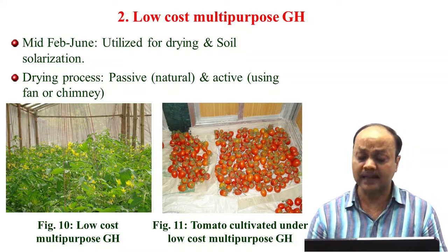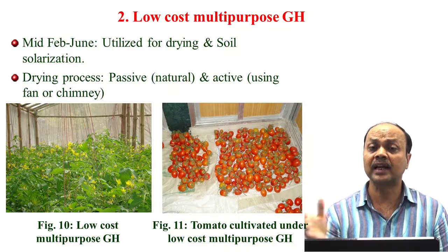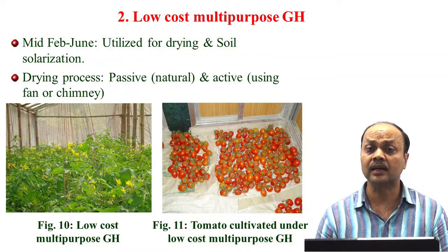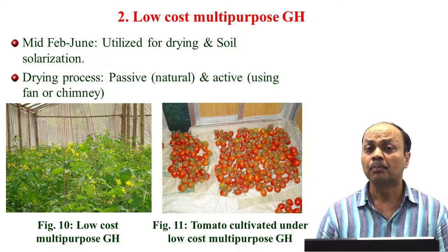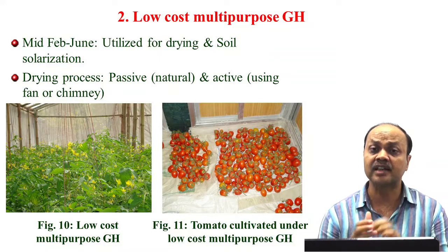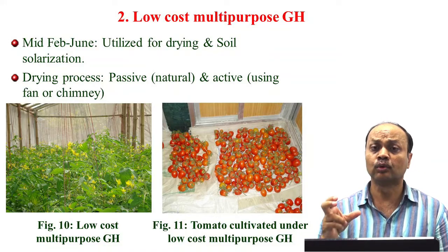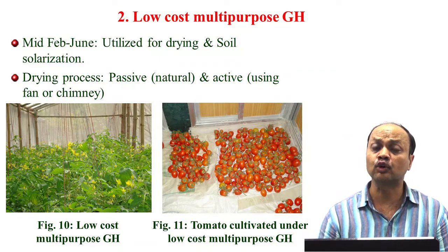So what I am saying, as I told you, is that due to high temperature we can harness it, but there are various factors that affect the drying. In this course, the other teacher will discuss them with you later on, but briefly I can say: temperature, relative humidity, air velocity inside the structure, and, depending on which type of crop you are talking about, the exposed surface area. So different factors affect your drying rate.